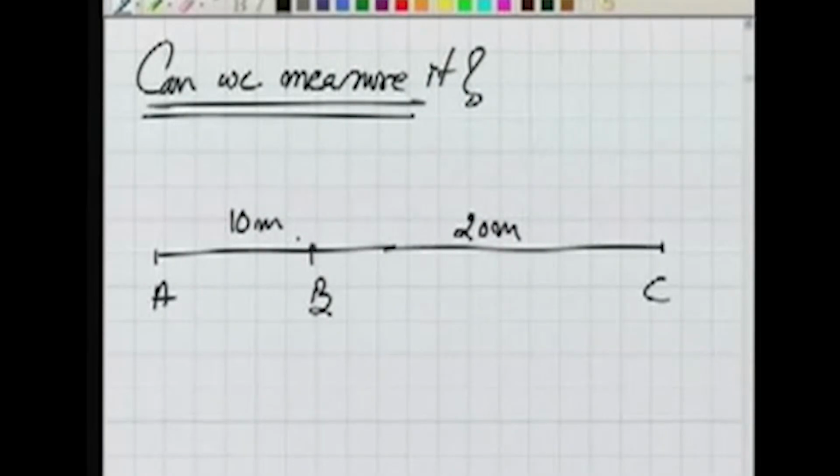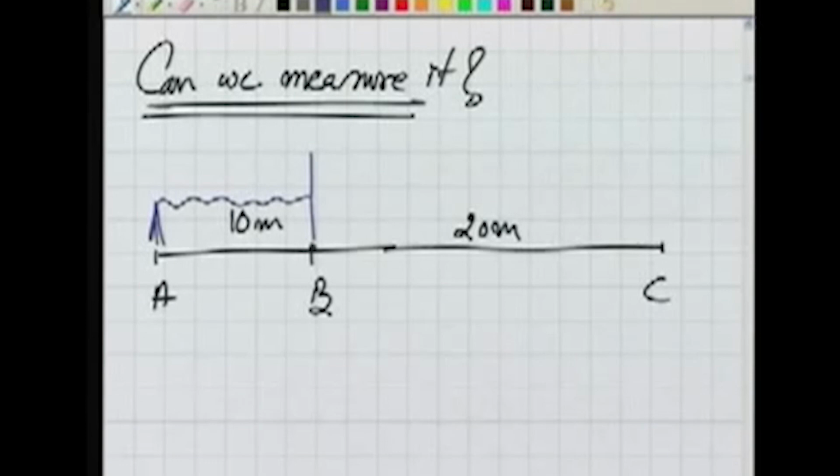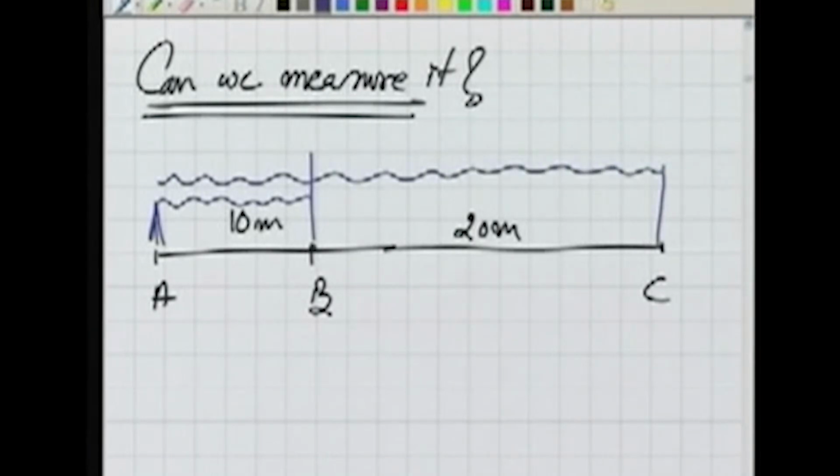It has been measured very accurately with some very good instrument, or an instrument which didn't have any error. Well, what we do, we keep our EDMI over here and we measure first this distance. Then we keep our target here and again we measure this distance. Also we keep our EDMI here and we measure this distance.